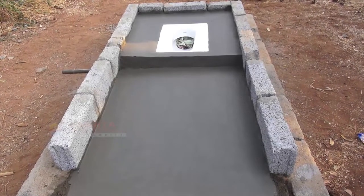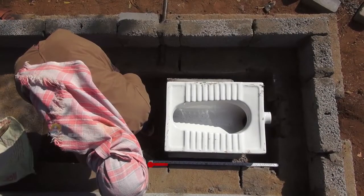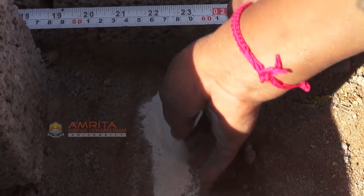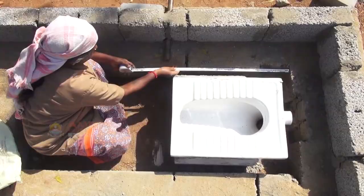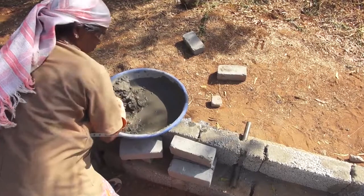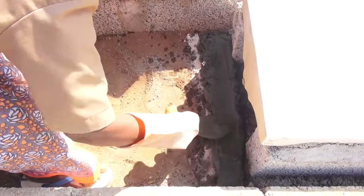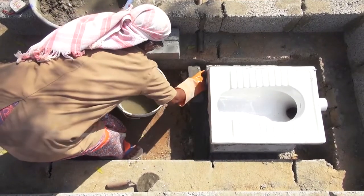We will now see the steps involved in flooring the toilet area. First, we measure and mark 58 centimeters from one end of the basement. This is to place bricks to pack the end of the toilet pan. Repeat the same on the other end. Join the two marks. Place 2 layers of bricks and pack with cement mortar. The brick is dipped in water for stronger bondage.